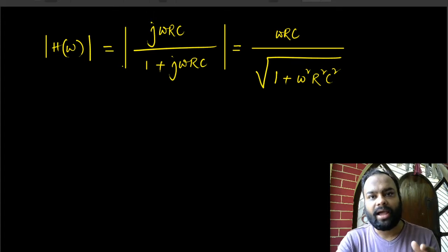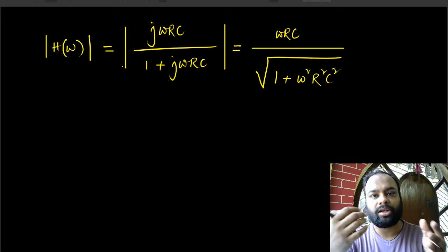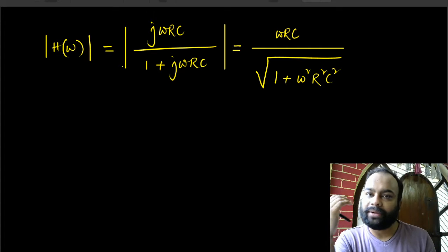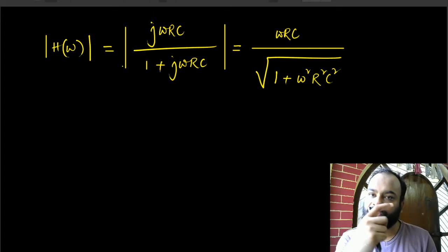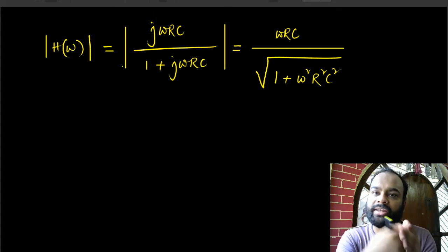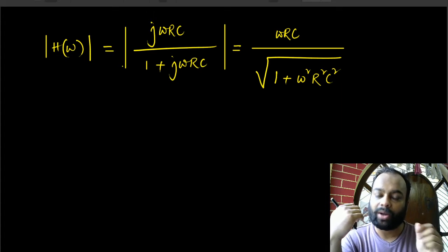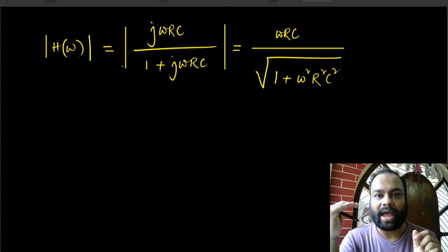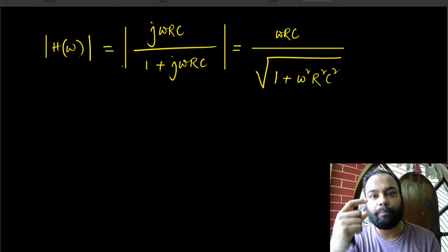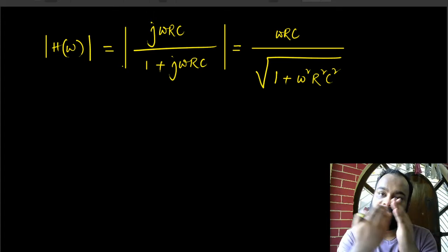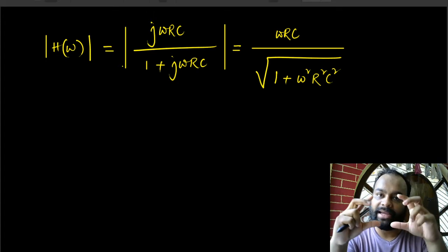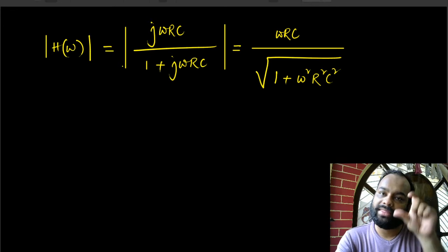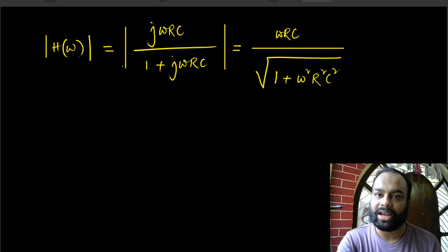That gives us a representation of the signal that tells me what the different frequency sinusoids present in the signal are, what their amplitudes are, what their phases are, and so on. If we know how the system behaves with every individual frequency present in the input signal, then we know how the system would behave with that input signal, whatever random input signal I have.